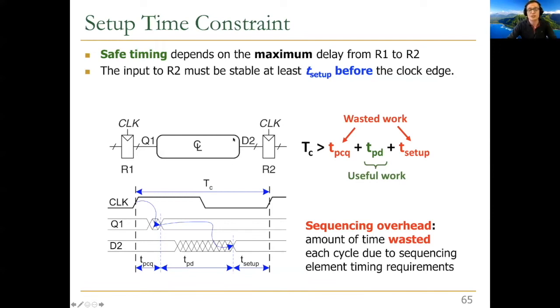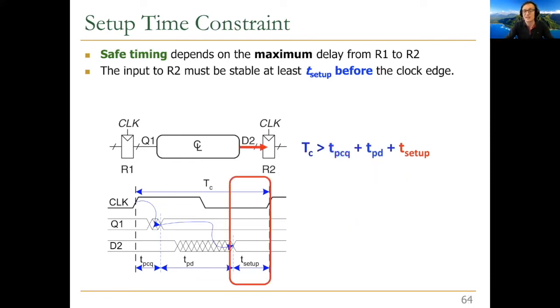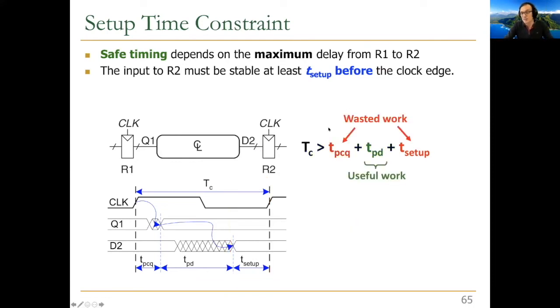and by separating it into multiple stages. For example, if you need to complete an addition, you can say, I'm not going to do the addition in 1 clock cycle. I'm going to do it in 2 clock cycles because I want to increase my frequency, so I do part of the addition in this clock cycle and part in the next combinational logic. That way, you can reduce the clock cycle time of the addition while satisfying the frequency requirements.